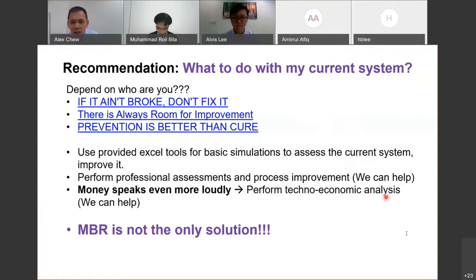If you have a minor modification and rectification in this MBR, we only do the notification for this part. We have to clearly highlight what the change in your plant is to the DOE. And the PE, the professional engineer, has to certify all this. You have to let the professional engineer sign and chop on Schedule number 3 and Schedule number 2. Hopefully that answers your question.